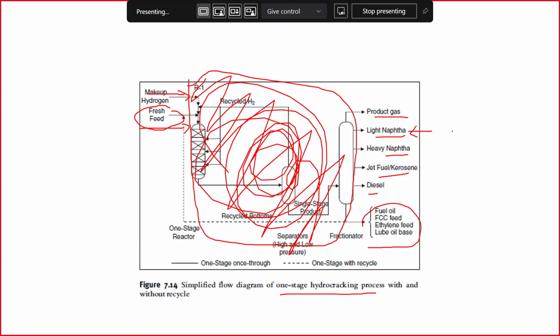We don't care how many carbons, what type, how much paraffin, isoparaffin, or aromatic is in it. What we want to know is the yield of naphtha only. The properties should simply behave like naphtha. We don't model the properties, we simply model the yield. That's where this lump model is mostly used.